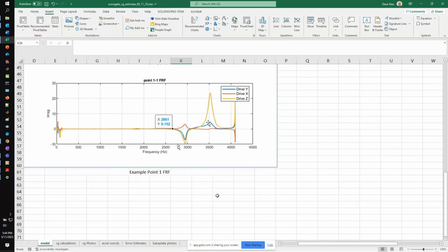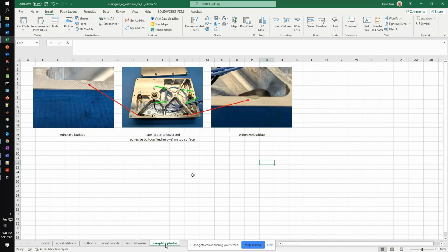Typically, if you have a nice uniform material, the damping or the response will look symmetric about the damped natural frequency. It looks kind of that way with the higher frequency mode, but if you look at the lower frequency mode, it's not. So there's some nonlinearity in the lower torsion mode. And I'll move over here. So what I found inside of our surrogate,